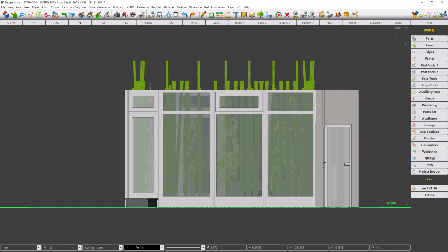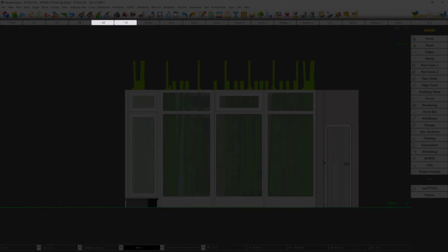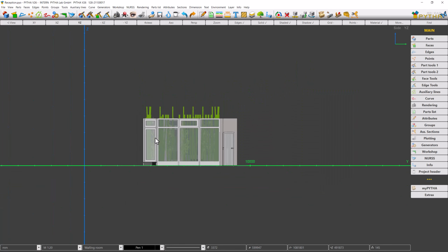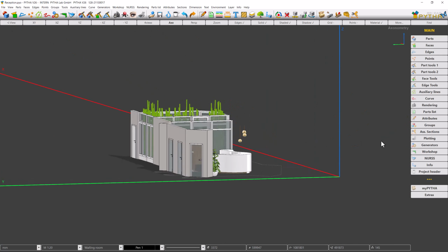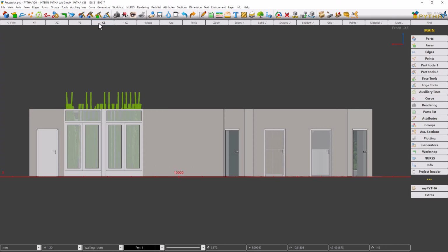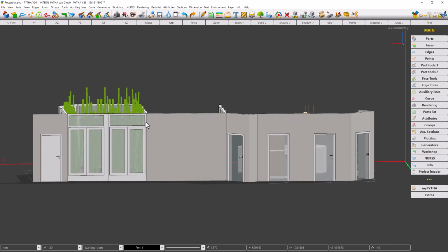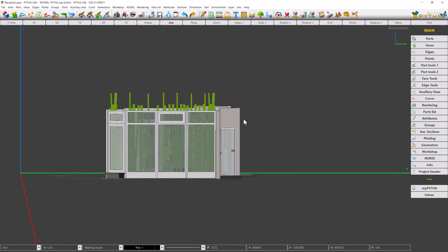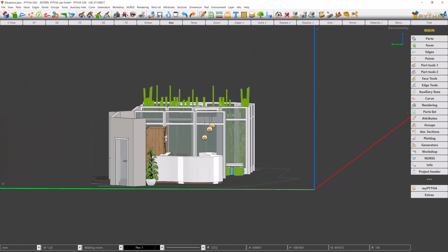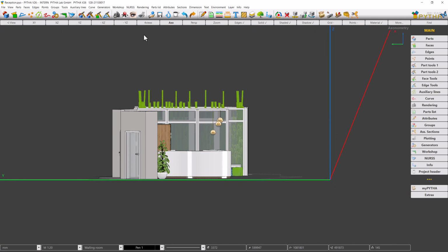You have probably already noticed that there are also buttons with a negative sign, so -XZ and -YZ. This is simply because we can view our objects from all sides. In addition to the front view, there is of course also a back view. This corresponds roughly to this camera setting. And you get there with the -XZ button. The YZ button shows a side view from the right, which corresponds to this camera direction. And accordingly, the -YZ button shows a side view from the left.